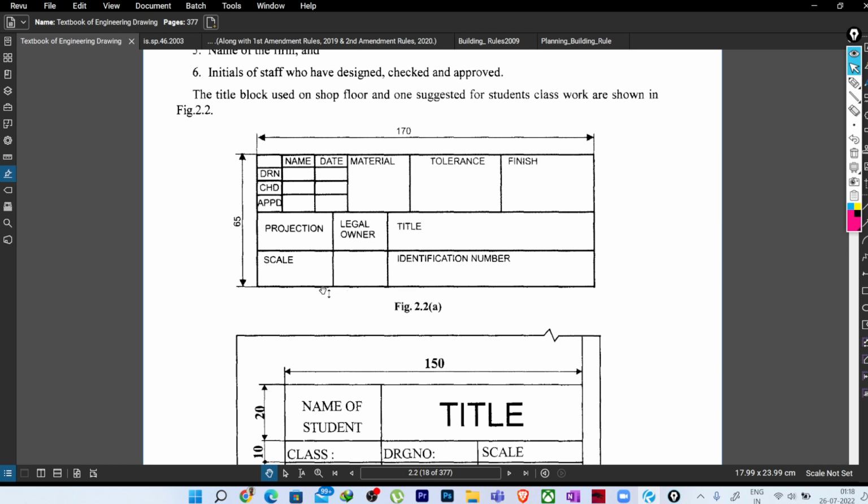Okay, the scale. Obviously, now in your drawing, suppose we have an A0 paper. Now one drawing we have at 1:100, one drawing we have at 1:50. So in that case you cannot mention the scale here, right? Because we have multiple drawings of multiple scales.